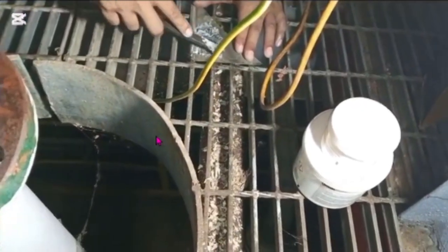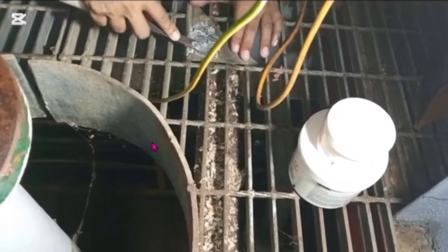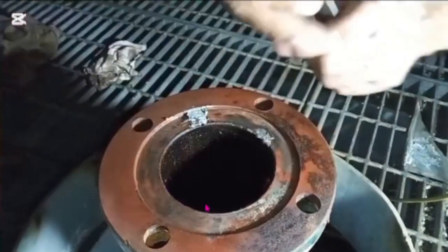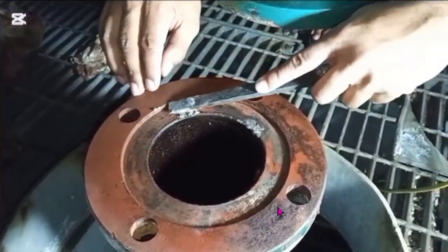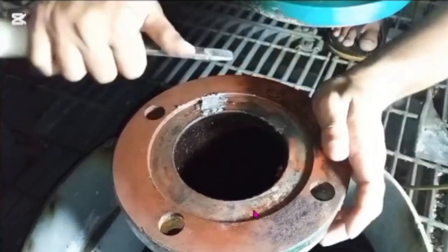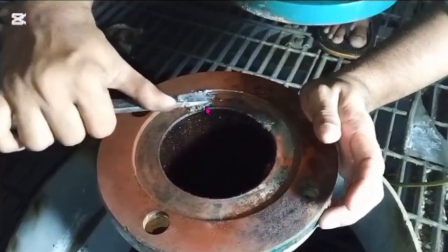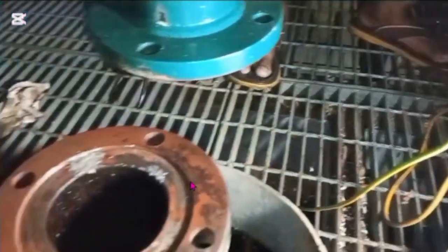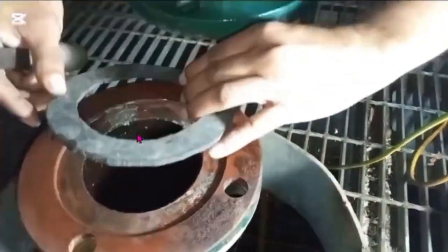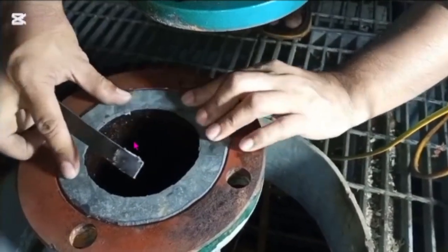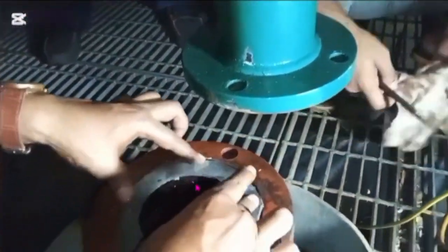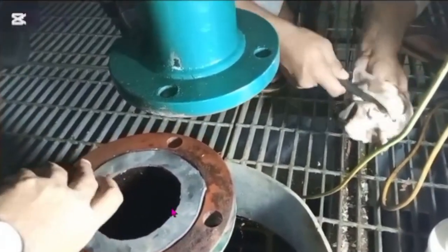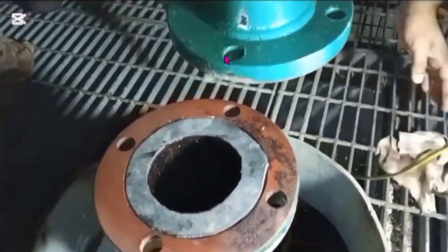This is to properly seal the vacuum inside the ejector, and on this putty there is somewhat of a hole, so we put the hardener here and then put the gasket here, and on this upper side we will put the ejector.